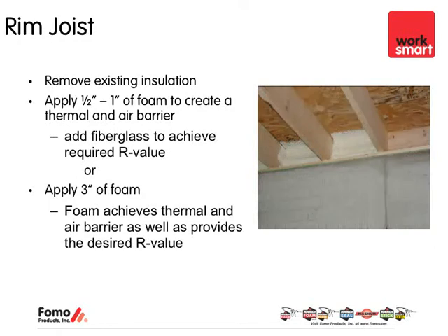You can then take, in a retrofit application, existing fiberglass bats and put them right back in place, or you could just foam 3 inches or more of foam, or whatever the code requires for R value in that rim joist. And if you need to cover it back up with ignition barrier, you could do so, or you could just keep it exposed.